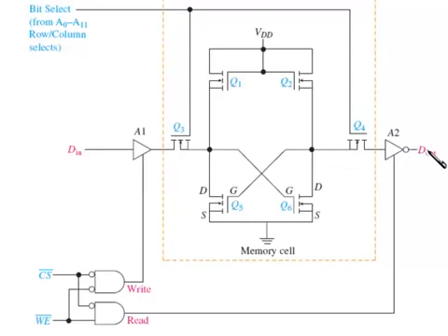I'm sorry, the 1 that came in turned this on, which pushed ground right here because it's a short, and the 0 comes through, gets inverted into a 1 again. So the D in that initially came in as a 1 is going to come out as a 1. So basically this is the functional operation of what takes place inside a single MOS cell. You have to multiply that by millions or even billions when you look at modern RAMs of today.